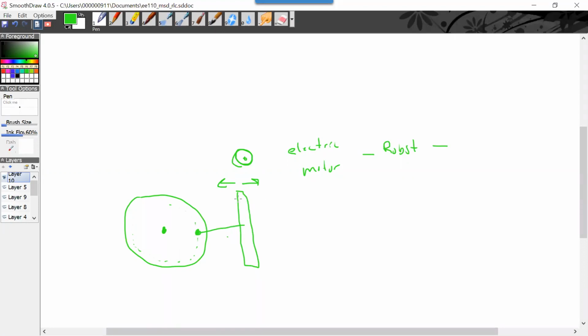So this physical system could be the moving platform. Here's a moving platform, and I have just drawn a rod, and then the mass is at the end. Well, there's no damping coefficient, you might say, but these parts bend. If you wiggle a metal rod back and forth, it does spring back and forth. And so you could be using your control system, like a microcontroller, controlling the position, but is the system overdamped, underdamped, critically damped? Could be really important to your design.